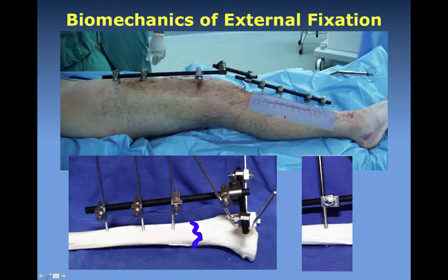This is a complex fracture where the fracture of the bone needs to be realigned, and in realigning it, screws need to be set in place along the length of the bone and then aligned. This alignment creates forces along these beam structures, pictured here and here for the upper and lower leg, respectively. And the analysis of these forces and the resulting moments that are generated by these forces help us understand how to best design these external fixtures so that they don't fail.